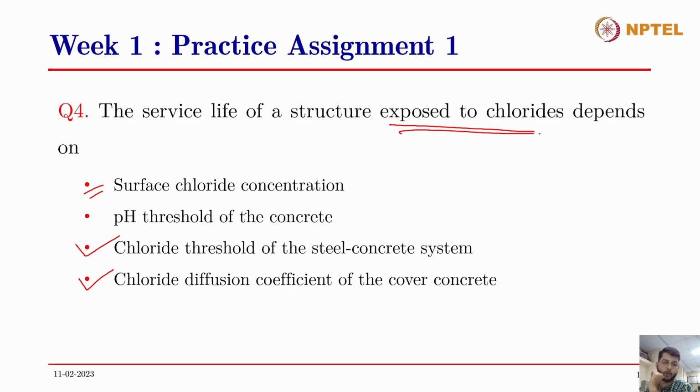Suppose there is an extreme case that there is no chloride concentration on the surface, so there is nothing to intrude into concrete. So as chloride concentration increases, only then does the case arise of breaking the film and affecting the corrosion process.